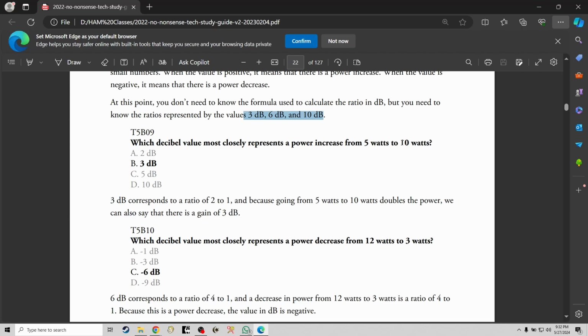You're basically doubling your power there. When you double your power, you gain about 3 decibels of the radio frequency power transmitted from your antenna. So when an antenna says it has a 3 decibel gain, it basically will turn, let's say, a 50-watt radio into a 100-watt radio. That is a very good thing.